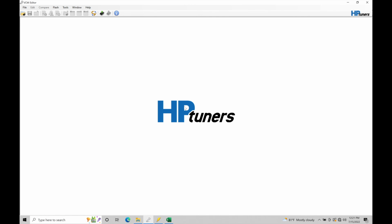I'm going to make your life a lot easier. We're going to be using a template applicator file found in our course folder to bring in and overlay the update changes we need to make. And then we're going to go through what those changes are. And then we're going to move into using our Excel spreadsheet calculator and then talking about how we can actually visualize what's going on with the variable cam movement from the array tables that we're going to be updating, as well as the distance tables. Those two go hand in hand to the map points. We want to make sure that the variable cam movement is going to be logical.